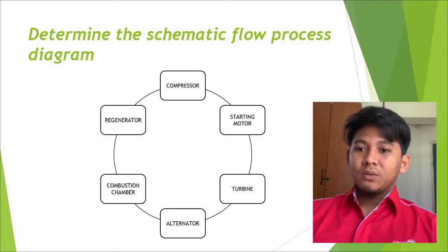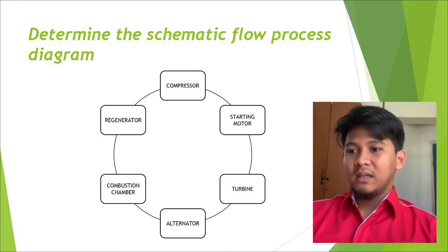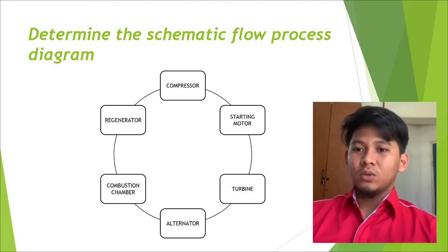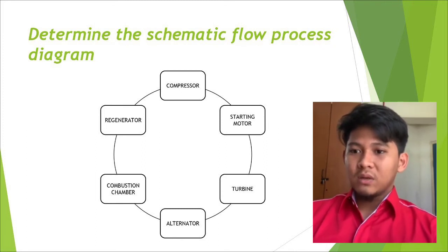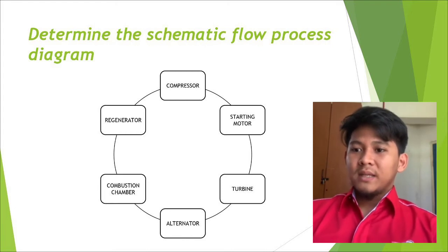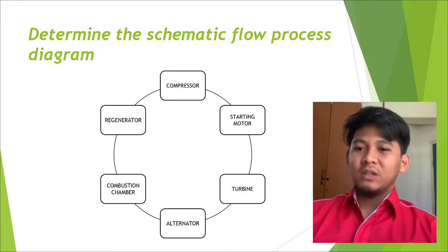Combustion chamber. After passing through the regenerator, the hot compressed air enters the combustion chamber. In the combustion chamber, there are burners through which fuel oil is injected in the form of oil spray. Due to combustion of this oil spray inside the combustion chamber, the air attains a very high temperature, about 3000 degrees Fahrenheit. The compressed air mixed with combustion gases then cools down to 1500 to 1300 degrees Fahrenheit before it is delivered to the turbine for doing mechanical work.